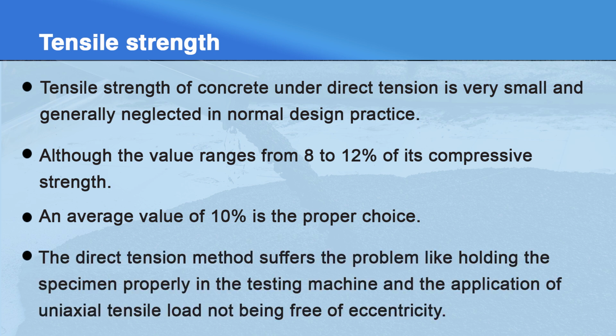The direct tension method suffers from problems like holding the specimen properly in the testing machine and the application of uniaxial tensile load not being free of any eccentricity.